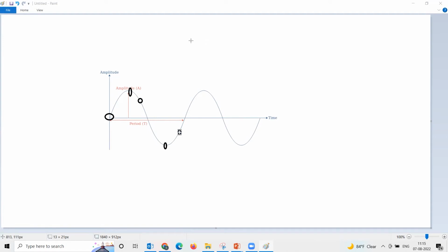So if we are able to find out the worst case, then we need to ask this question: worst case, is it a maximum value or is it a minimum value? It's both, in fact. Maximum might be the worst case for selecting the switchgear rating. Worst case might be for selecting the cables, for sizing the CTs, and maximum value for many other studies. But the worst case could be minimum also. The worst case could be minimum for your other studies like harmonics, and, what else? To check the sensitivity of the protections, right?